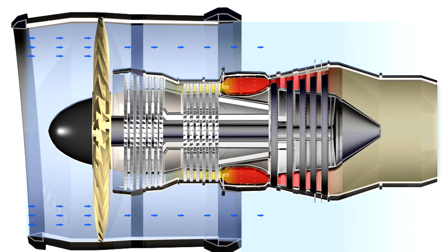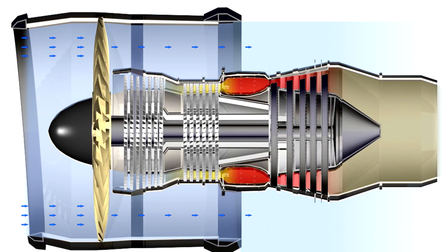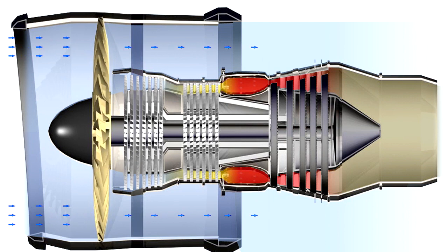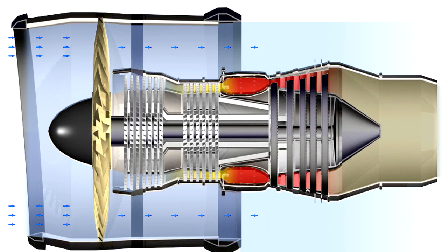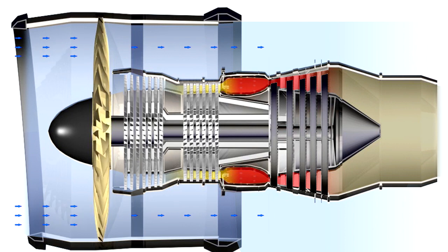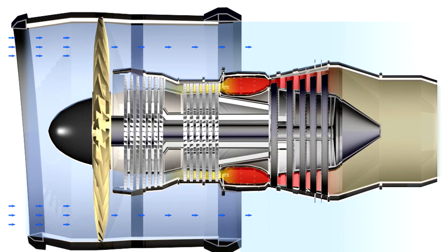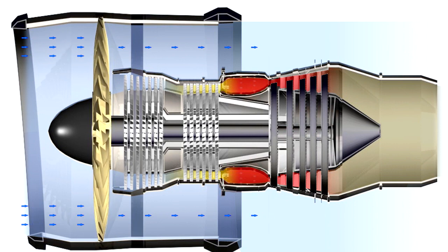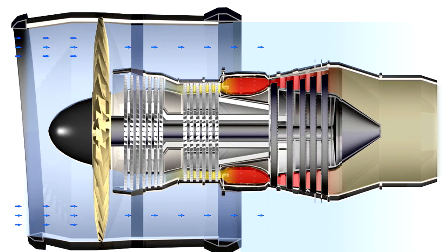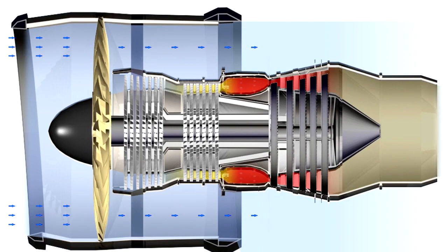When the aeroplane reaches speeds in excess of 0.2 Mach, then the air ahead of the engine starts to compress, increasing the air density, and therefore increasing the total mass of air flowing through the engine. As a result, this helps to limit the loss of thrust caused by intake momentum drag. This thrust recovery is called ram recovery or ram effect.